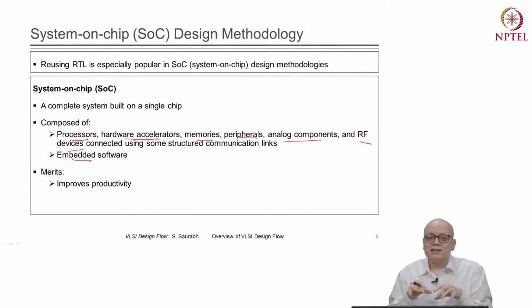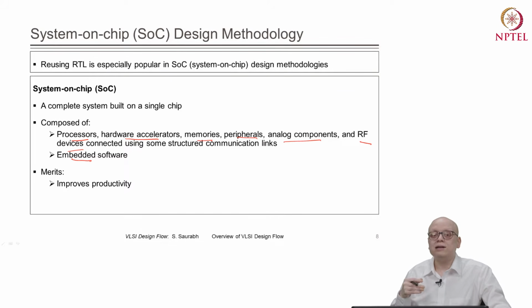So the designer's task is not designing a complicated chip in which each individual component is designed, but only integrating those components and of course verifying it. This is a simpler task than designing each of the components at the individual level, and that is how we get improved productivity in SOC based design.